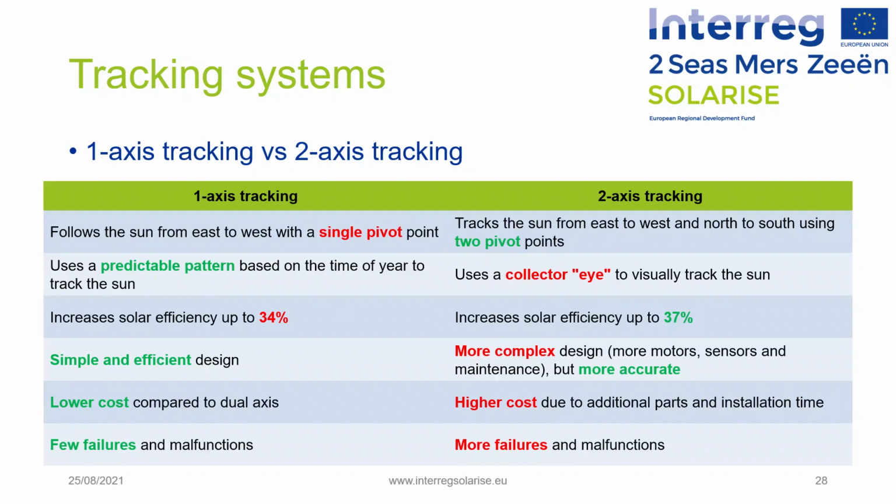Finally, the dual-axis tracker can also have the disadvantage of pointing up into the sky on a cloudy day, whereas single-axis trackers, thanks to their tracking model, will be where they should be. The single-axis tracking model therefore eliminates unnecessary tracking movement that causes additional wear and tear and power loss. The commercial opportunities represented by the single-axis tracking technology are thus more present on the market.